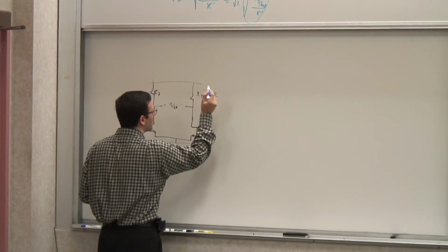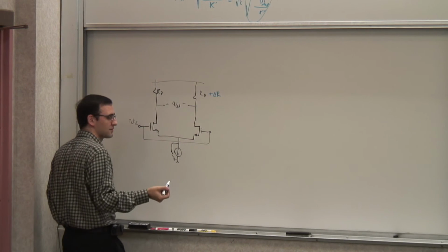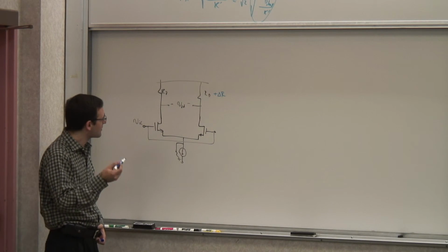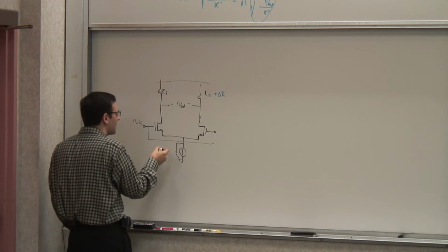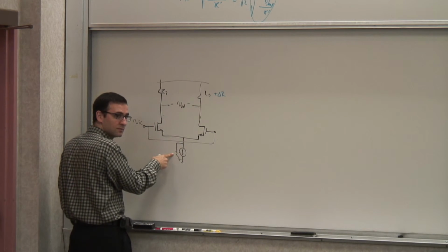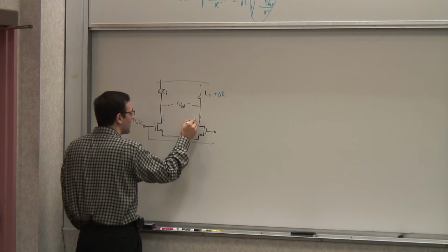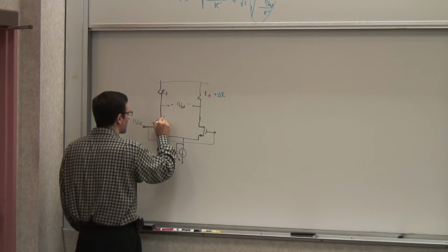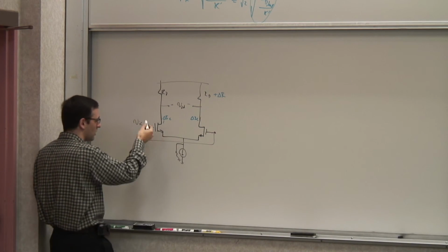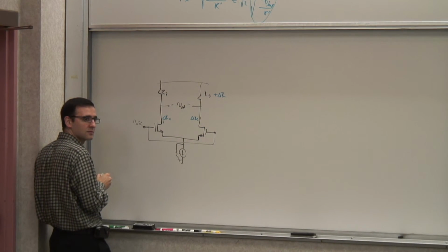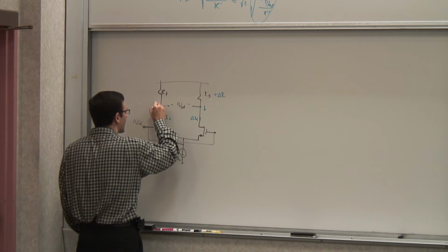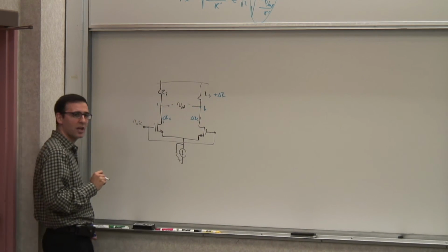Let's just look at our resistance, and there could be a difference in the transistors. Now, when you have something like this, let's say the resistors are different. So you apply a common mode voltage. This current goes up a little bit because this resistor is finite, and this current goes up by a certain amount. So there's a delta IC, which is proportional to VIC. But now, this voltage goes down a little bit more in this one for the same change in the current.